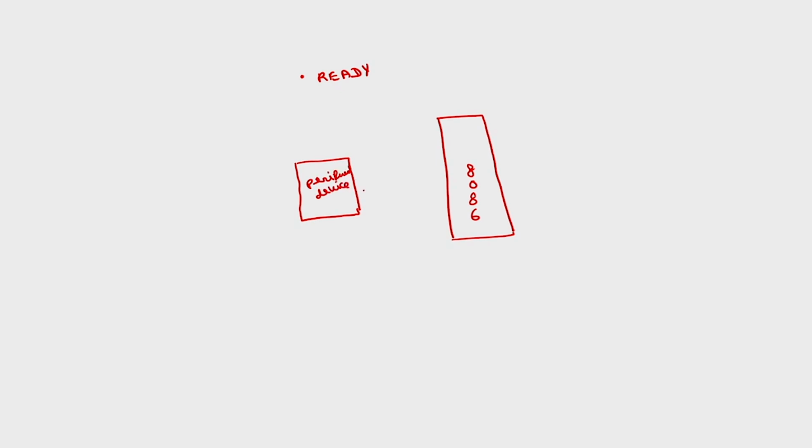If the microprocessor receives a low on the ready signal, that is ready is 0, the microprocessor will enter into the wait state.